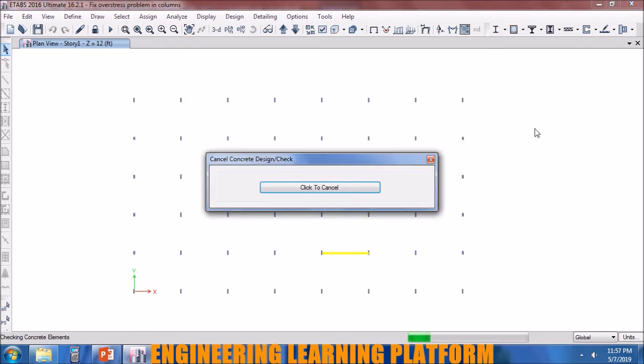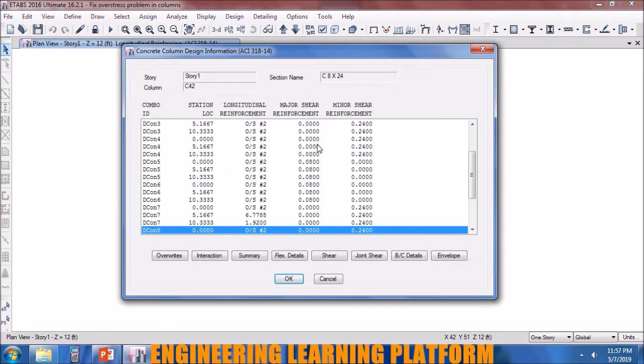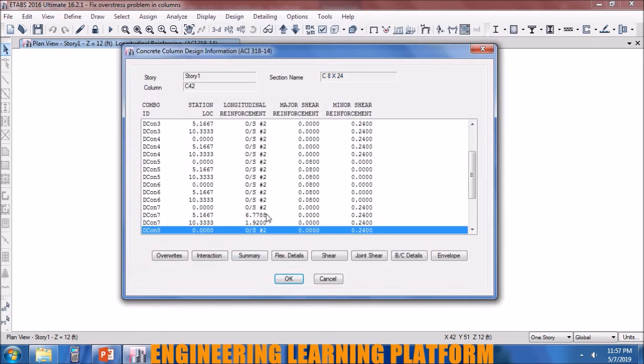So that the beam will be designed in order to absorb all its moment, transferring to its main steel. But the detailing of joints shall be using the particular type of framing, IMRF or SMRF. So you see still the columns are failing due to cross section.